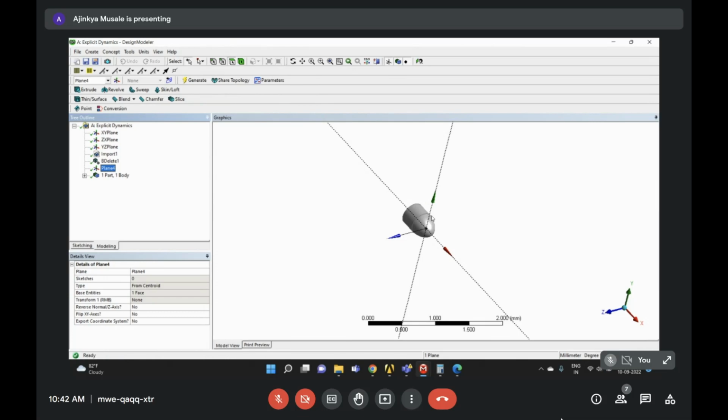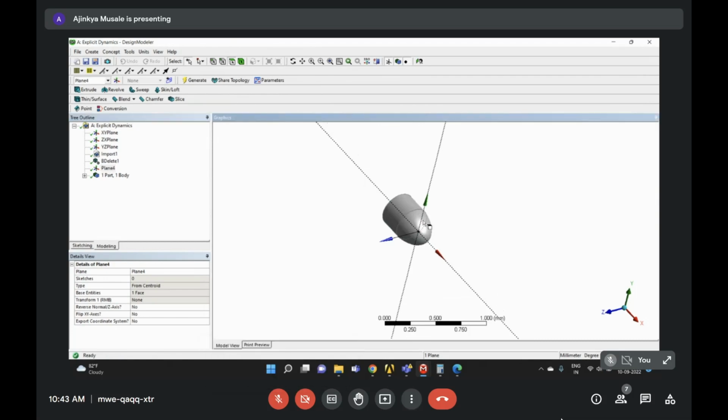So for that I need to rotate this one so that my x will come this way and y will be vertical. Why? Because here in Design Modeler, I can only sketch on the XY plane. No other plane. So the XY plane of the local coordinate system. Okay. So what we will do now, we will try to rotate this plane, and we will try to get the x-axis as, like I am having Z now, and my Z in that case will come at my x-axis location.